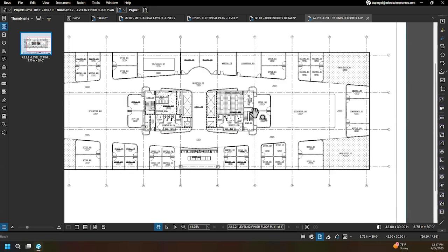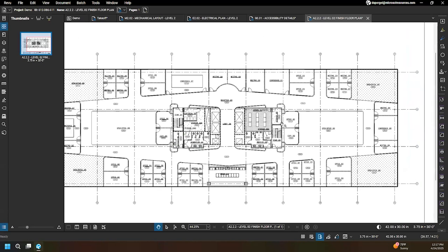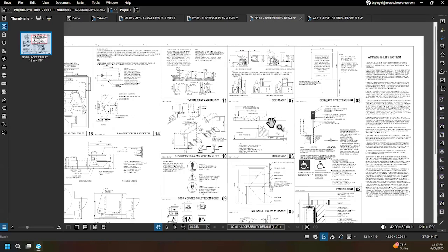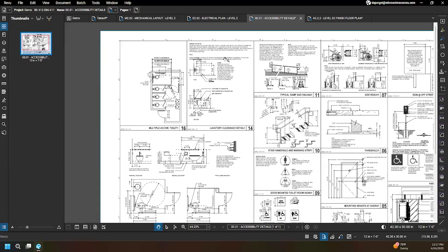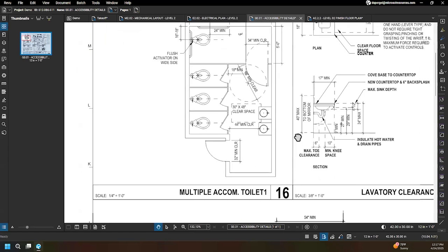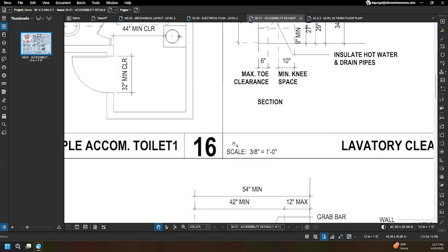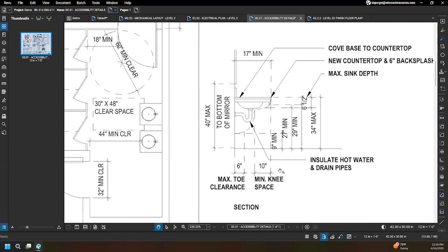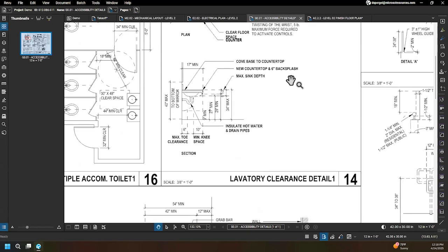But sometimes you have a page that has multiple scales on the same page. So this is pretty common when you're looking at maybe different profiles, like a top-down perspective and then a side profile in a drawing. Also in detail pages. So for example, a page like this with the accessibility details, where each one of these detail sections has its own scale. You can see nicely noted over here. They also have a number of dimensions that we could use to calibrate their scales as well.